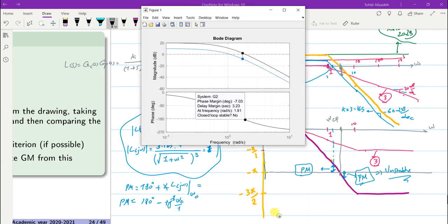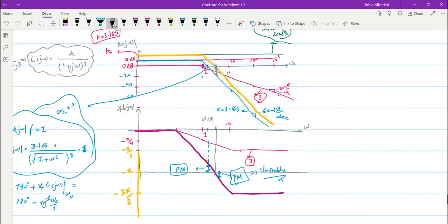And you can see here the gain margin for two cases. For the first case, the gain margin is positive. It's equal to 8.6 decibels. And for the second case, which is drawn in black, it's negative -1.94, which means that our closed-loop system will be unstable.